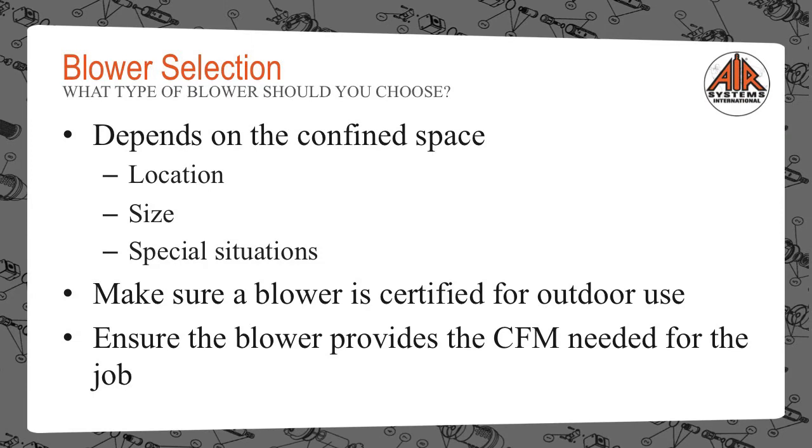Now that we understand the basics of confined space ventilation, let's discuss the most commonly asked question. What type of blower should you use? The answer will depend upon the confined space. Let me explain why. There are so many confined space situations, locations, sizes, and other variables that there's no one-size-fits-all solution.